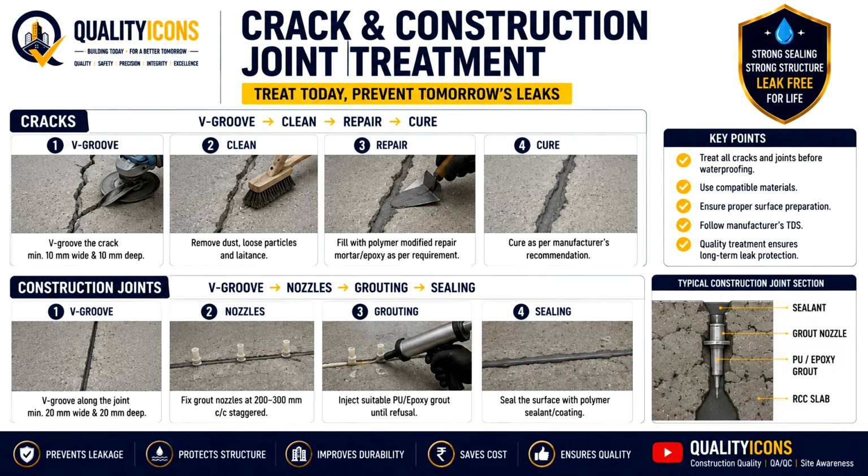Coming to crack and construction joint treatment. After the initial bonding acceptance, cracks and construction joints need to be treated. For cracks, the typical sequence shown here is V groove, clean, repair, and cure.